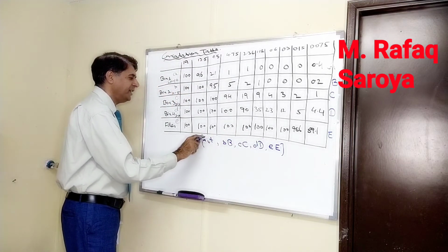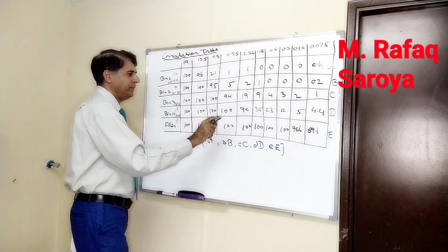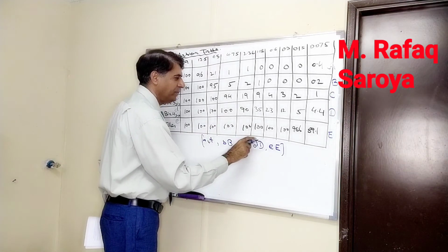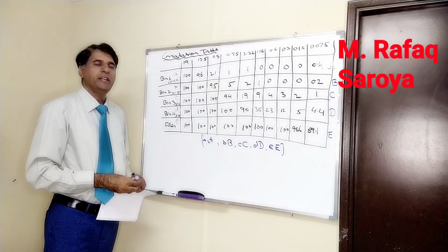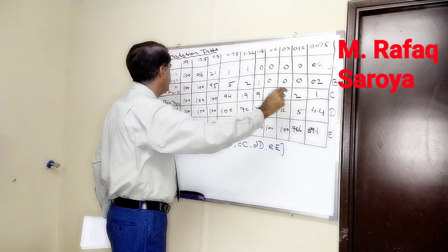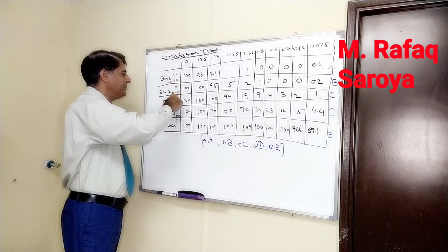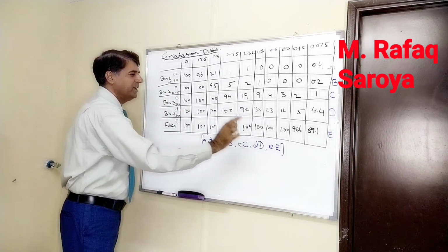It means passing percentage into fraction, for each sieve. Clear? So A, B, C, D, E are the passing percentages. These small a, b, c, d and e are the fractions. We have to get the multiplication of them.